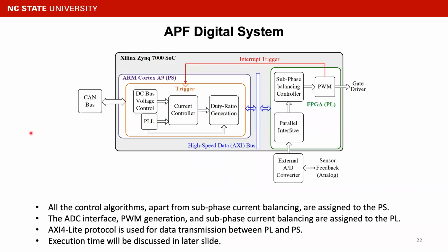And here's the digital system design for our active power filter. As you can see, all the control algorithms, apart from the subphase current balancing, are assigned to the PS side here.